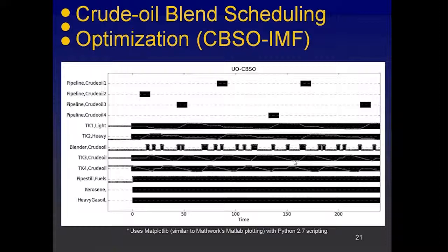So you have at least 19 hours where the quality of the material going into the crude unit doesn't change. So you can start to hone in with your advanced controls and start making great product. And then of course you have problems when you switch over between different tanks, but that's another story.